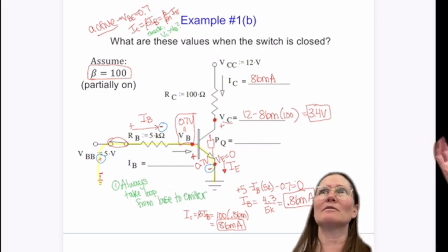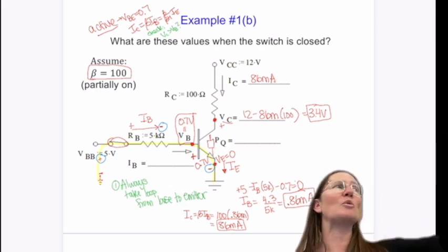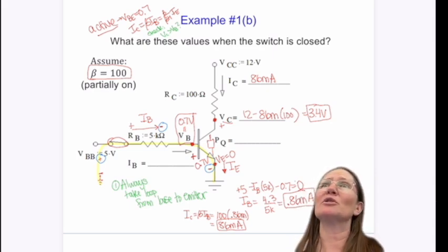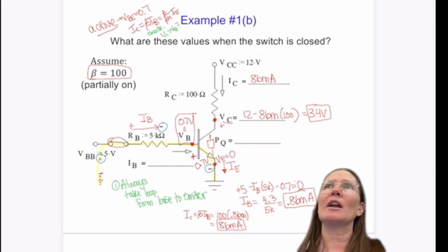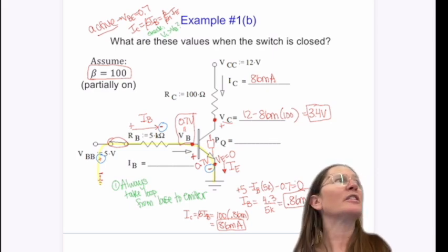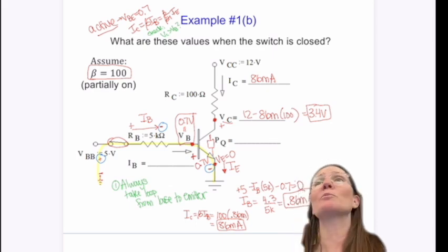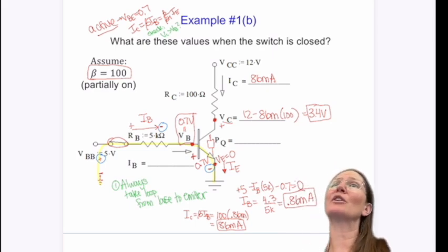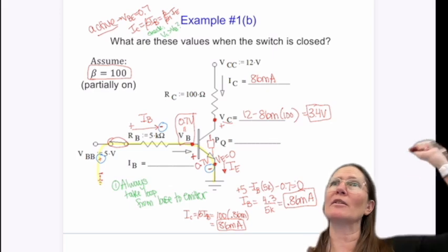So that's one thing to know as far as a concept wise, like yes, internally there's a diode when it's on between the base and the emitter, and it acts like a normal diode of 0.7 volts drop. But we also know there's some current that flows there, and then we don't know there's a variable kind of diode in between the collector and the emitter. So that's an unknown voltage because it varies over how much current comes in.